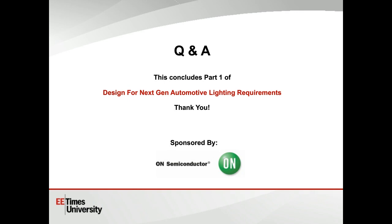Because these LEDs, again, as we'll see tomorrow, these state-of-the-art LED headlights have multiple LEDs with beam forming. So, for example, you'll have an LED headlamp assembly that illuminates everything around an oncoming vehicle, but not the oncoming vehicle itself, to avoid glare. Those types of things need a tremendous amount of controllability in the LED and steering of the beam, and it's really not a question of just swapping them in and out.